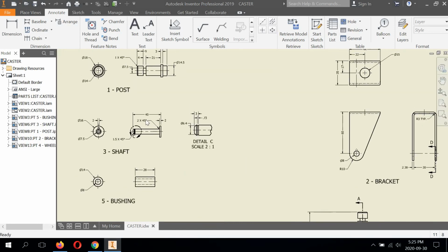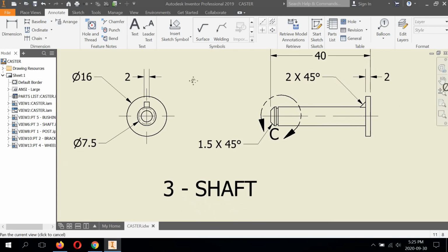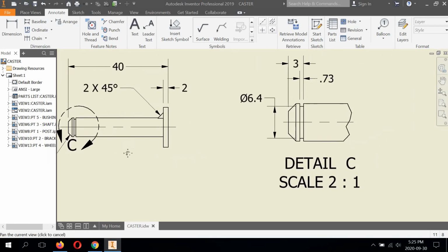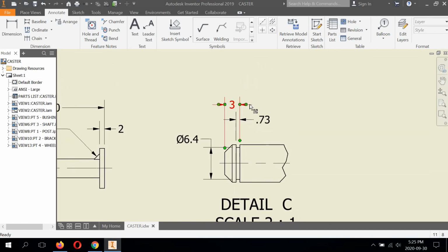One last thing you can do is look around and make sure that dimensioning spacing is very consistent. You don't have some dimensions sticking way out and some way close. So for example, this one could be moved out a little bit more to suit what we have here.